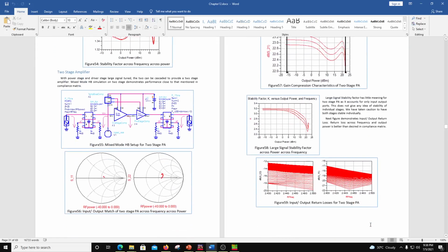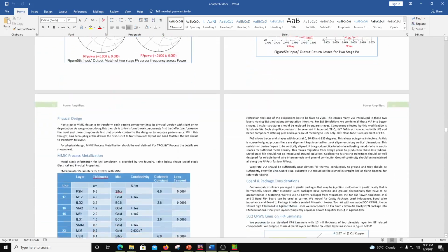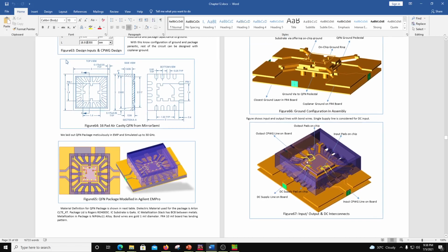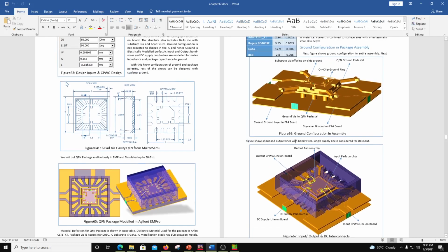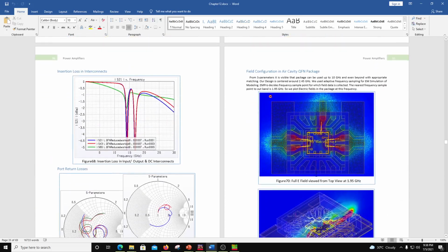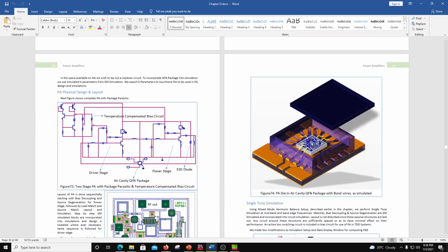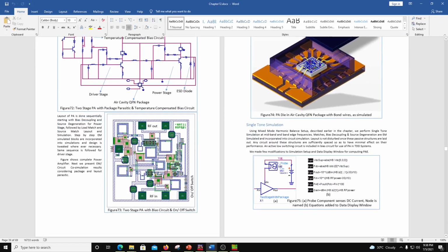Yeah, it has to be that band, 2.4 to 2.5 gigahertz. And that's the thing which you have seen, right? This IC goes inside. So basically for me it starts with interpreting this design of a QFN, right, in which this IC is going to sit, and this IC is going to be like this. Okay, so basically here is the top view of the layout here, right?